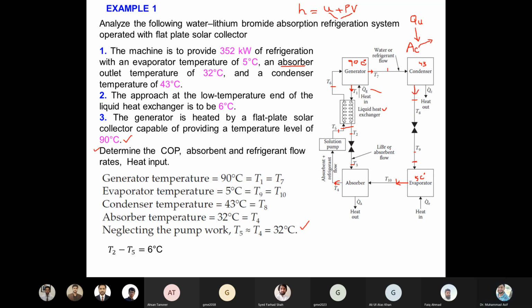Okay. But sir, in this case, we are calculating enthalpies from the chart, and if we are using the same temperature and same pressure, how did we conclude that these two enthalpies are different, sir? It is the same. You can ask the same question: how come you are adding heat into the refrigerant without changing the temperature?